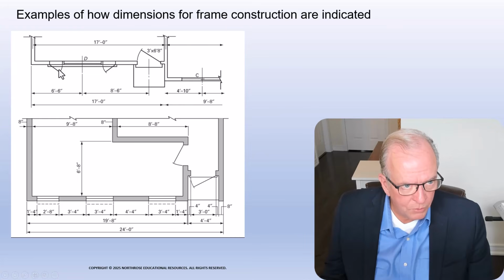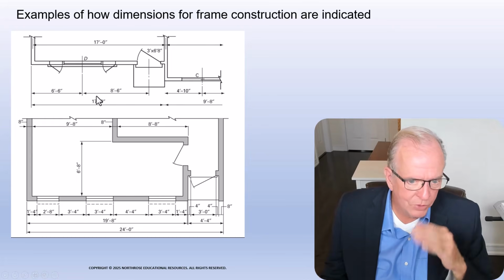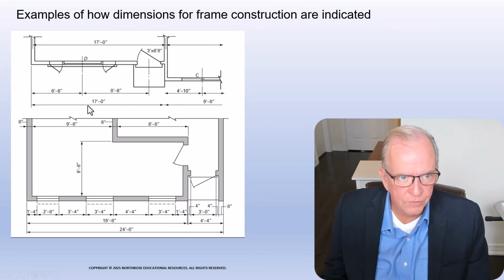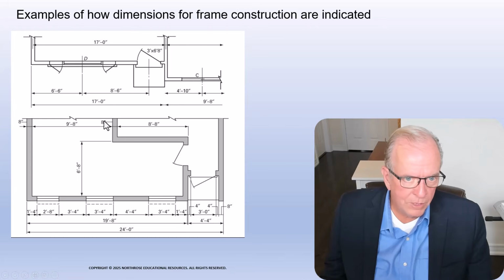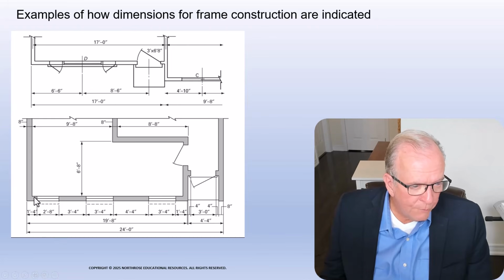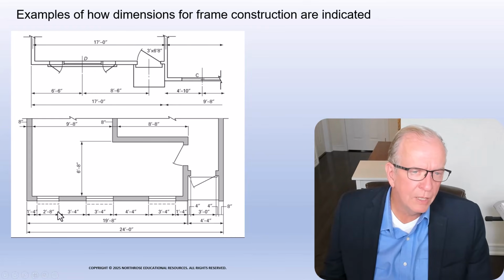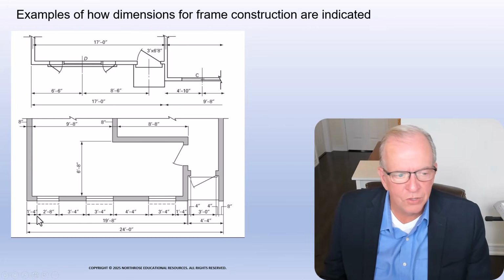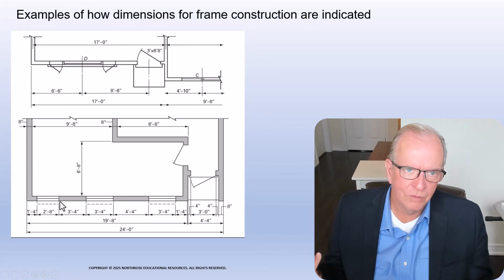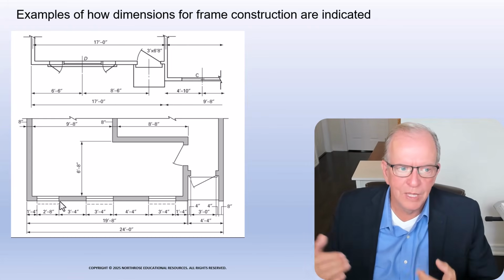These are casement windows, and this is the center line. You can see this is using arrows in this case. I said we usually use slashes, but in this case, the sample from the book has arrows. It's pretty clear where it's going from and where it's going to. So in a lot of cases you may find the measurements for the extension lines go to the center line. Or in the case of masonry, solid masonry like brick and block or precast concrete, very often it goes to the edges. You just have to look at it and you'll know. I'm not going to tell you it's always this way or always that way, because it depends.